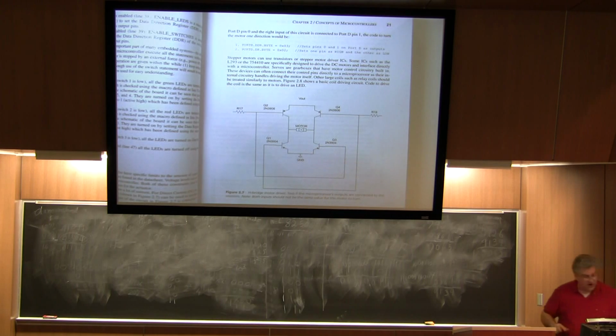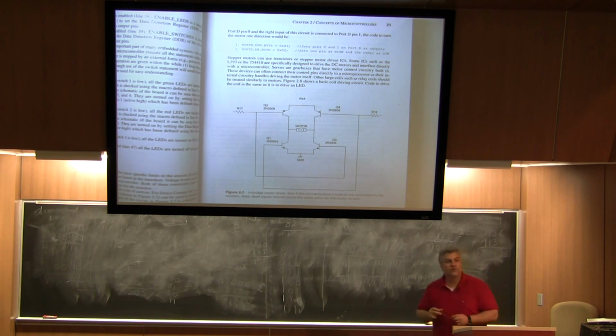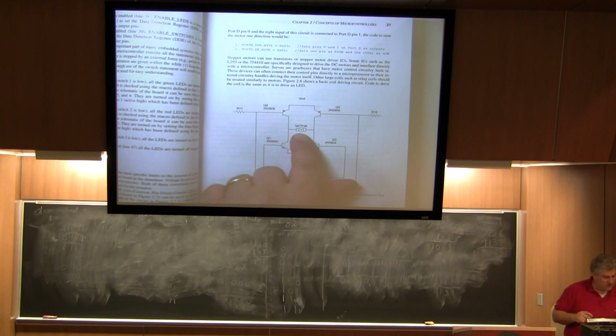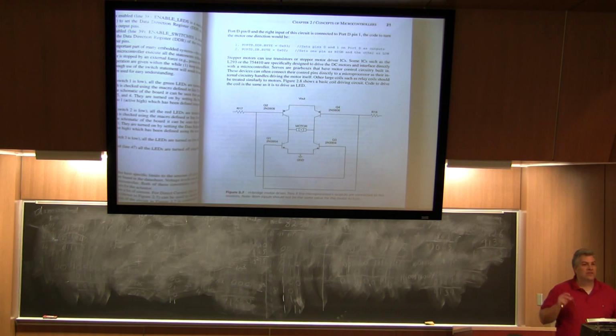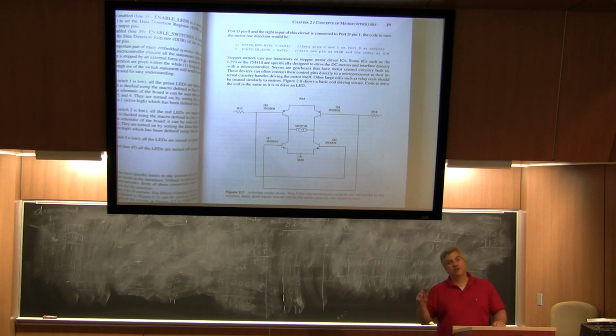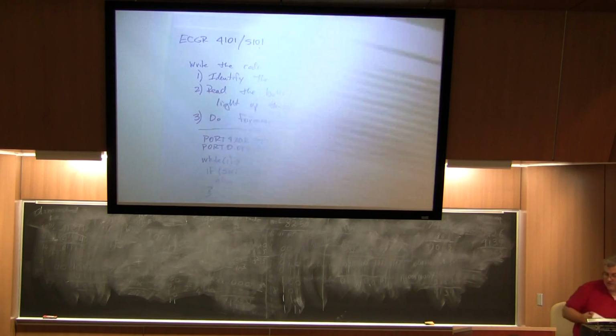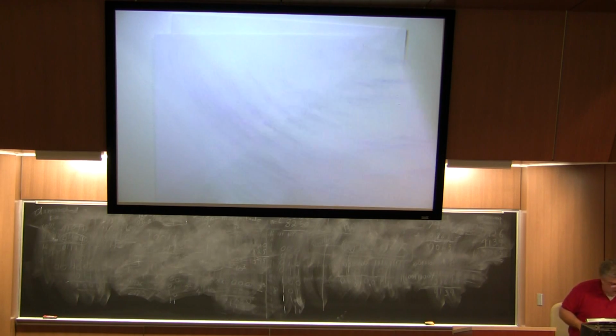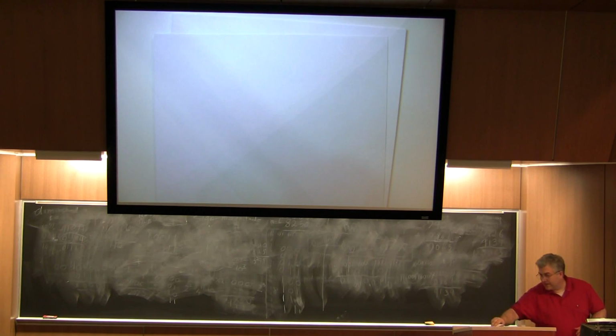These transistors are going to be the workhorse of driving motors. Forward and backward, on and off. There's your motor. So this is an example of how you don't want your microcontroller to directly drive a motor because it doesn't have enough current to be able to do that. If you do try and do it, typically you end up with a little pile of silicon goo that doesn't work out too much.